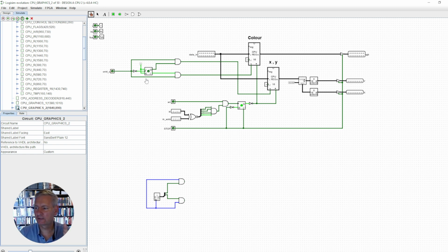Now, I designed the circuit again using a D-type flip-flop, which is just like a little counter. So we can replace this with a little counter, which looks like this. I've put this in here, and it does exactly the same thing. You can actually see that the counter changes from a value of 1 to 2 without there being any change in the clock. The clock just remains at 0, but it counts another 1. Now, there's not any race condition, and there aren't two values changing at once at an input. There's nothing else happening here.